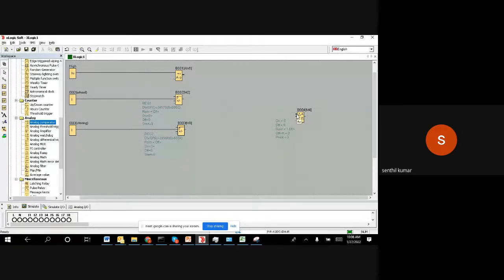When you connect any value, like if you want to compare a value with some value, then the value which needs to be compared you connect in the first leg, and the next one you connect with the other value against which you want to test, right? Always it checks when this value is greater than, less than, or equal, and so on. So it always takes the first value as a reference. If this value is greater than or less than this, that's what the comparison takes place, and then based on that the result will come.